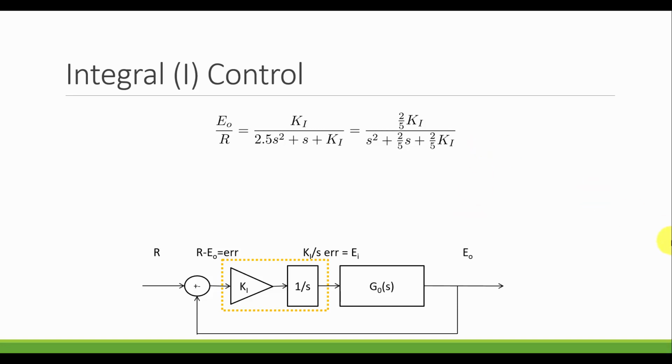So putting it into standard form, since we have a second order system, I want that leading coefficient to be 1, so I can divide everything by 2.5. I'll work with this form of our closed loop transfer function instead. Well, we can look at the poles, because those are just the zeros of the denominator. And we can see here what it's going to turn out to be.